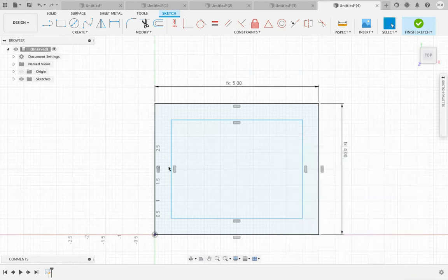And then I can say, set this side to be inner length. The problem is, when you start changing the dimensions of your box, you're always going to have to remember to change this outer number and this inner number. We really want to just change one and have the other one change for you.